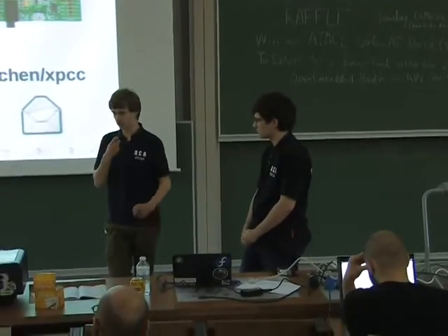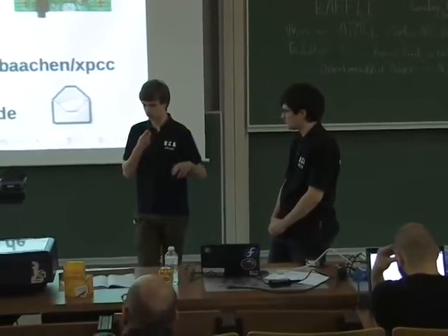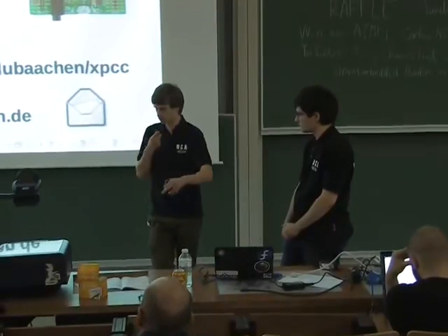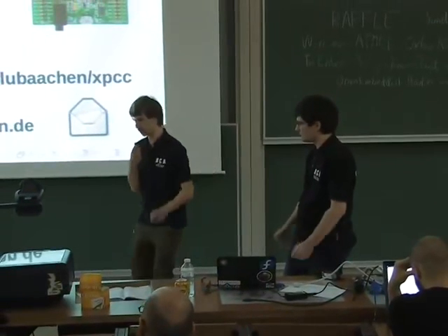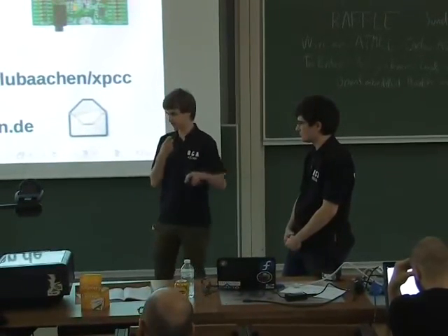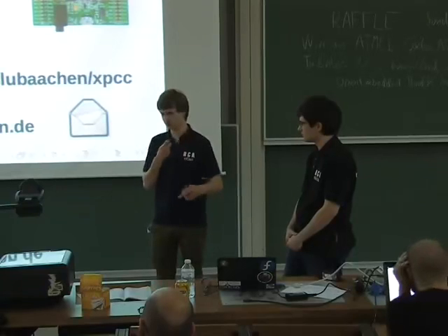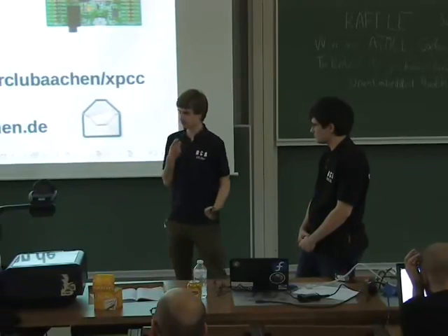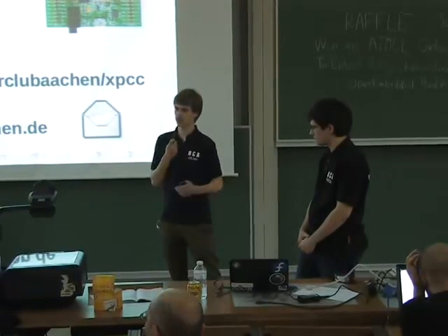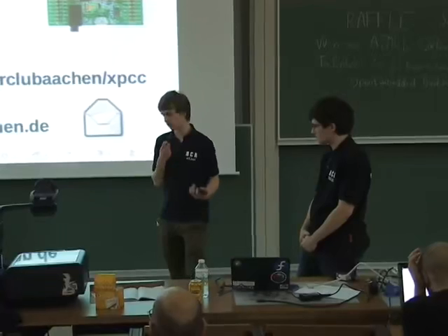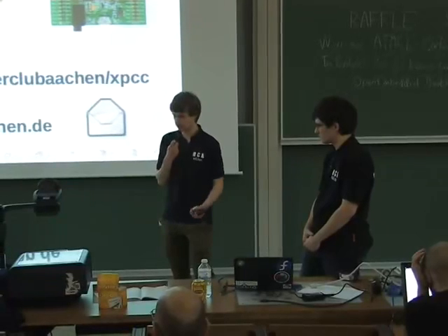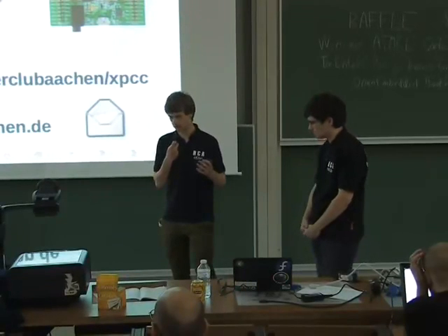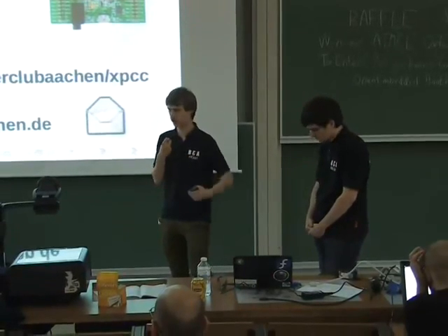And so what you get, for example, on AVR, is a simple assembler command that just sets your port high. So it's a little bit of overhead compared to writing registers yourself, which is kind of ridiculous for those big devices. But if you compare it, for example, to a C++ library that doesn't use link time optimization, our stuff is most of the time better, because we use a lot of static stuff like templates, and we try to inline our code.